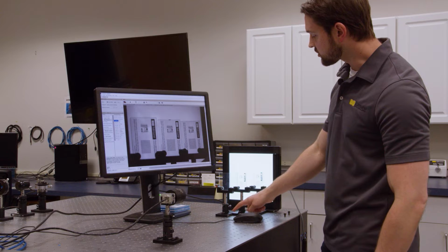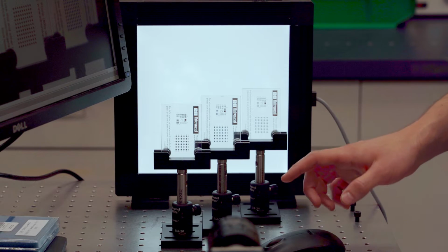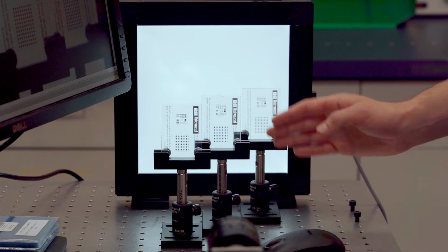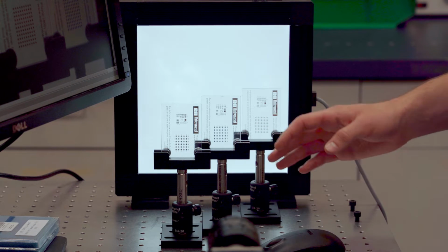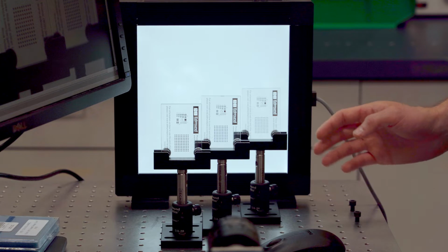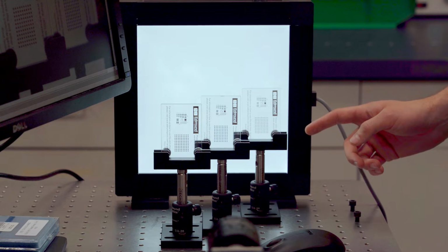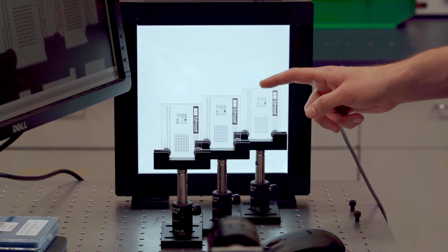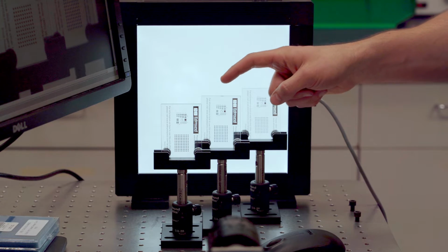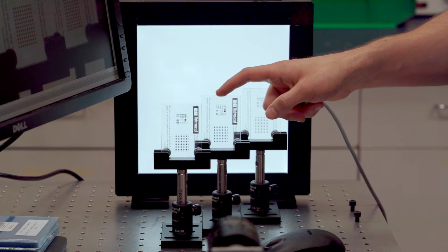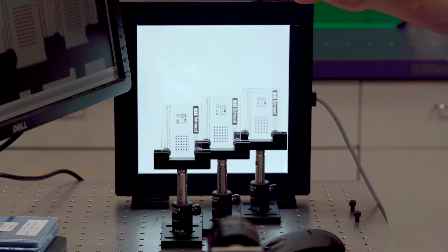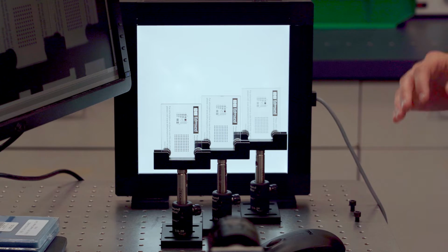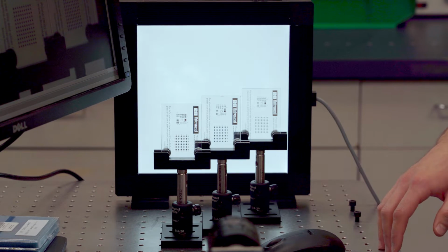Then I have three different targets back here, and these targets are USAF targets. I'll explain what that is in a minute. I have them stacked vertically, with 2 inches between each target, so we have a total of 4 inches. The target in the center is in the center of the vertical grouping as well. This lens is currently focused on the target in the middle. For illumination, we have an Advanced Illumination 8-inch side-fired backlight, giving us a really nice even illumination profile right now.